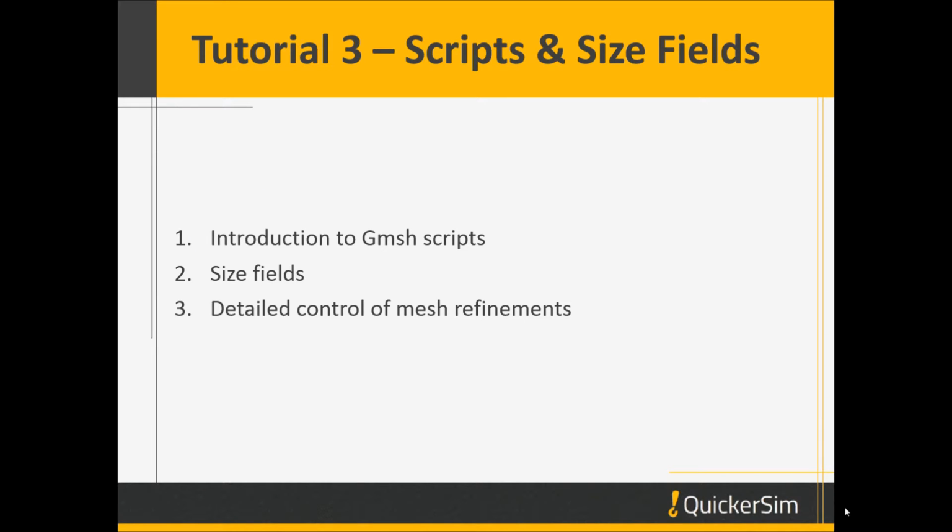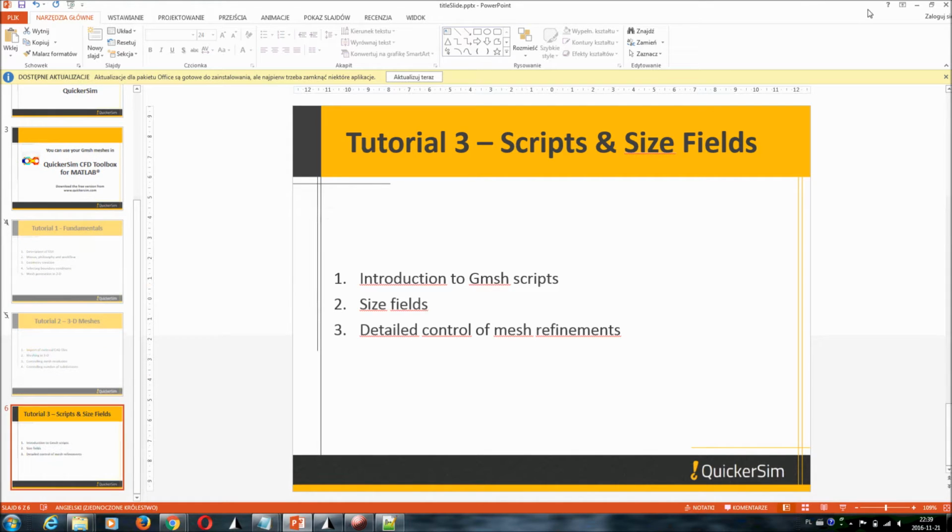In the third tutorial, we are going to make a step towards more advanced features like writing scripts and defining size fields, which give you very detailed control of your mesh resolution. So at the beginning we are going to talk about an introduction to Gmsh scripts and then about size fields. Alright.